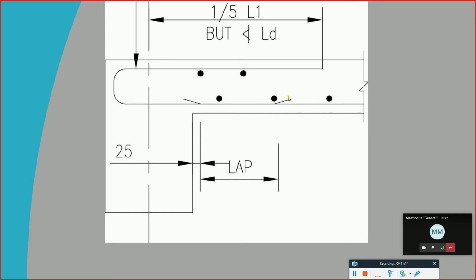After that, we need to have the connection reinforcement between the slab itself and the beam. So we need to provide reinforcement which is called the minimum or top, which starts from here and goes to the top. We said how much is the value. The value is going to be first 50% of the main.